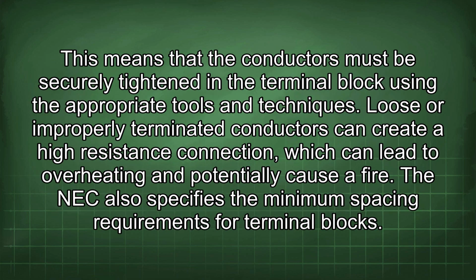The NEC also requires that conductors be properly terminated in the terminal block. This means that the conductors must be securely tightened in the terminal block using the appropriate tools and techniques. Loose or improperly terminated conductors can create a high-resistance connection, which can lead to overheating and potentially cause a fire.